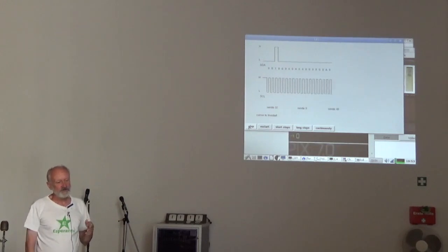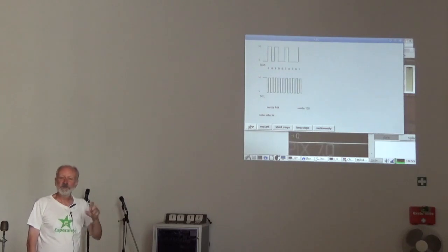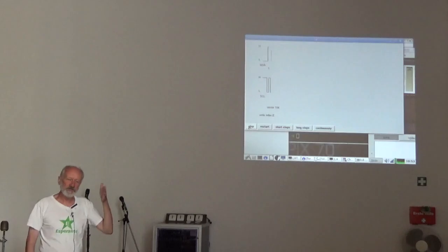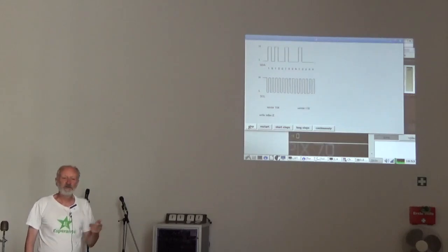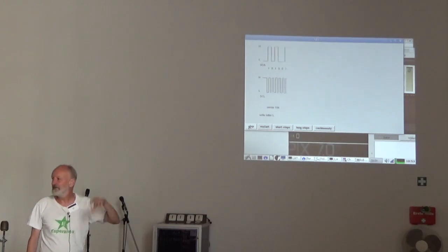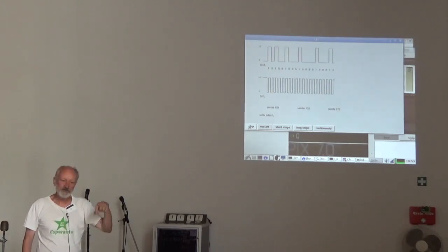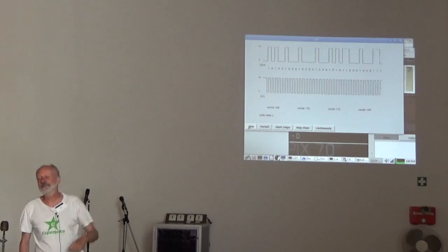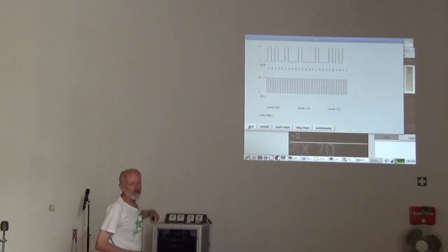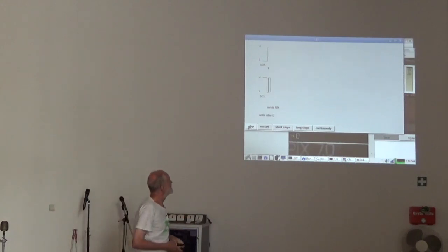You can send the bits to the LCD module at various different times, but only when the bit pattern has reached the correct state and you toggle the enable bit is the data put into the LCD chip. So it starts again with hello world.